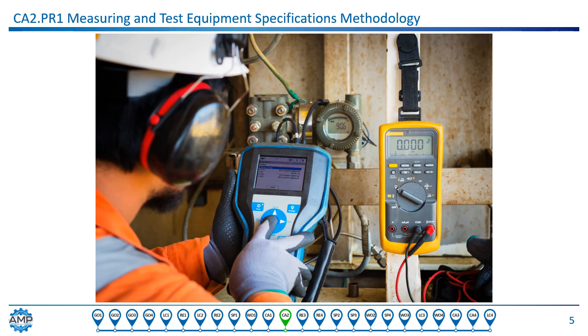However, an instrument is installed in the process that has a tolerance of plus or minus 5 degrees, and we set it at 95 degrees. We could easily be within our instrument tolerance of between 90 and 100 degrees and constantly be challenging the process limits anyway. For whatever processes we can talk about, regardless of industry, instrumentation must be designed with all process parameters in mind and how tight the parameter tolerances are in operation.